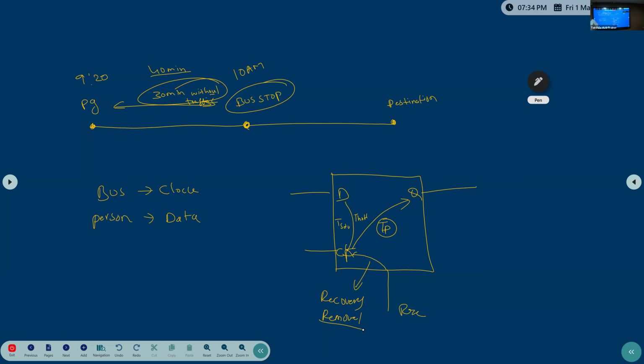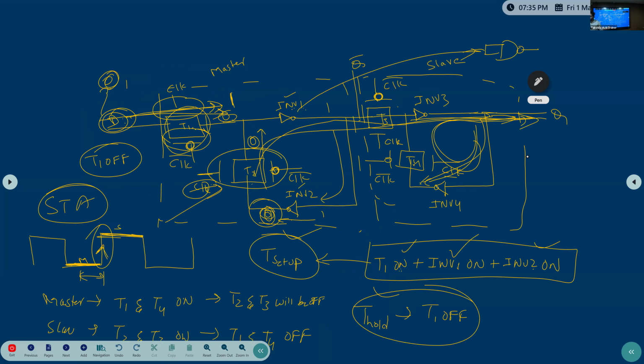When we start STA, all this timing arc information will be there in the .lib file. The J Bhaskar book will cover it. J Bhaskar's book is a very high-level, number one book. If I want to suggest one for STA, that is the J Bhaskar book. In the second chapter of that book, this will be there. That is very important. These timing arcs will be there, and if you understand these timing arcs, you can understand STA very easily. Simple, nothing is there. Is there any difficulty?